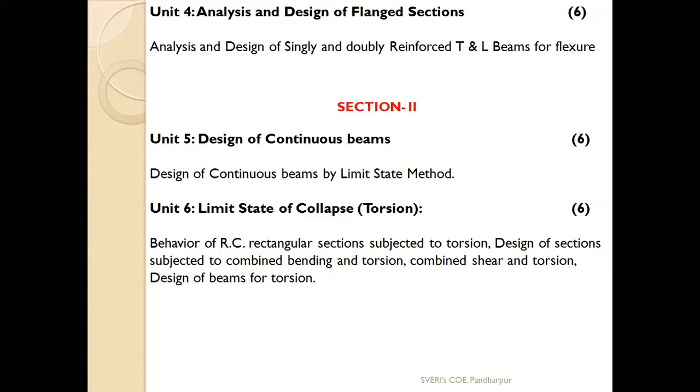Although these formulas are known to you, sometimes the situation may arise that you need to calculate the bending moment at a particular point, and when you come across this type of situation, you must be clear with your basic concept. In that, you need to calculate the reactions first, then take a section at the point where we need to calculate the bending moment, then consider either the left hand side or the right hand side, and then by using our conventional sign conventions we calculate the bending moment.